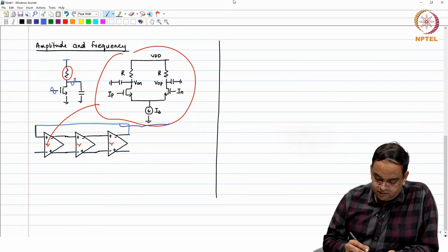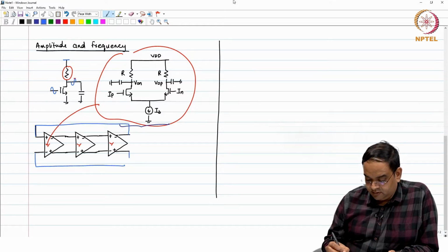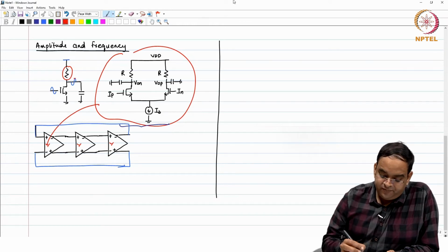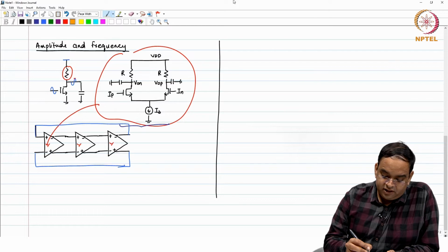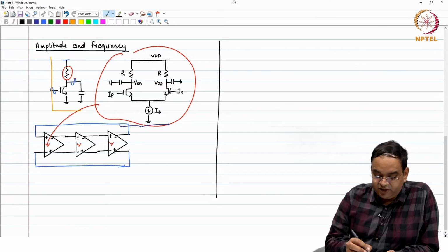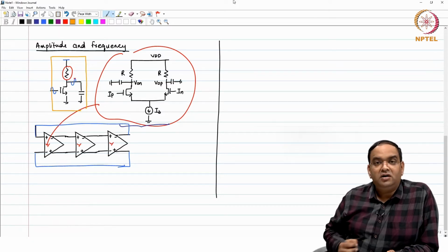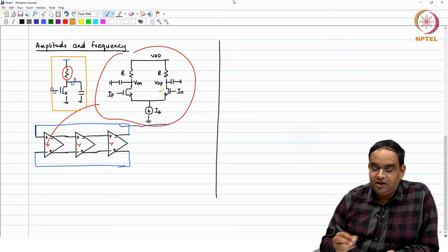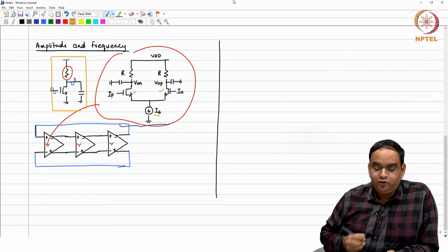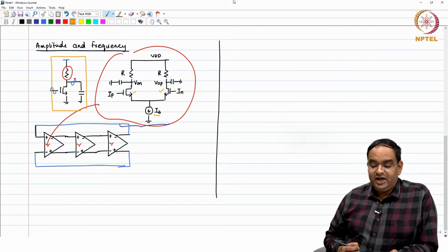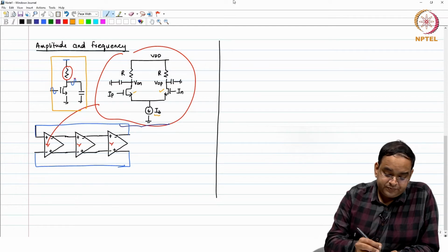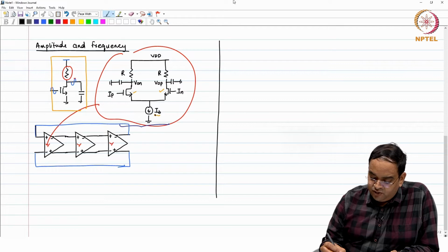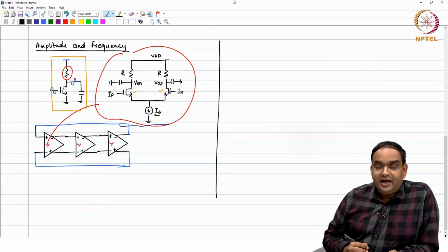Okay. It will make an oscillator. So, what I have done is, I have created, you can say, first just a mirror image of this, which you are seeing here, and then fixed the current source which is supplying the current to the cell. Now, for each cell if you look at IP and IN, you have a fixed current IB.